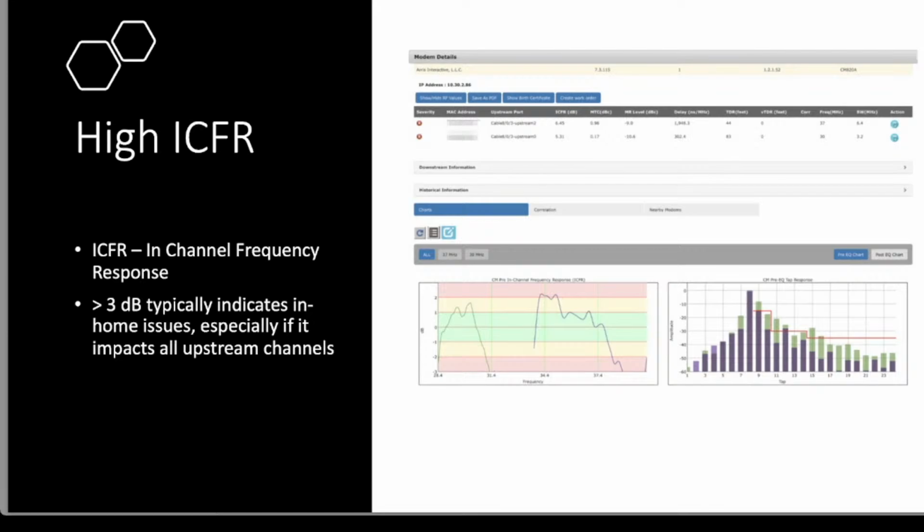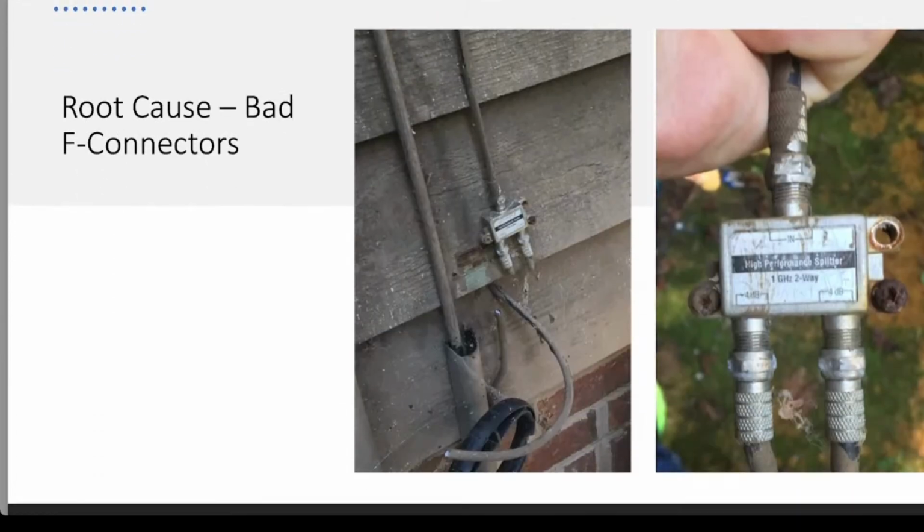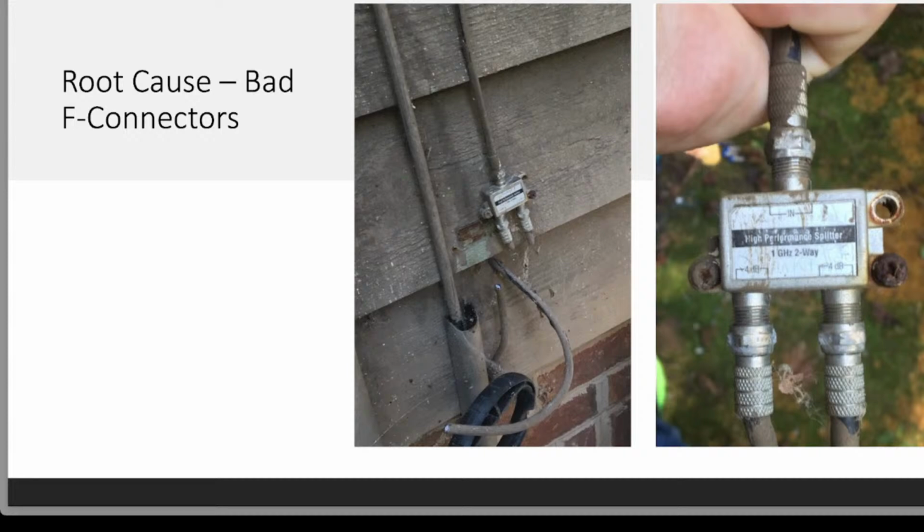Could even be at the tap. In this particular case, I'm going to show you what the in-home problem was we found. Here we see the source. It's bad. I think we normally call these twist-on connectors. So you can just finger tight these connectors.